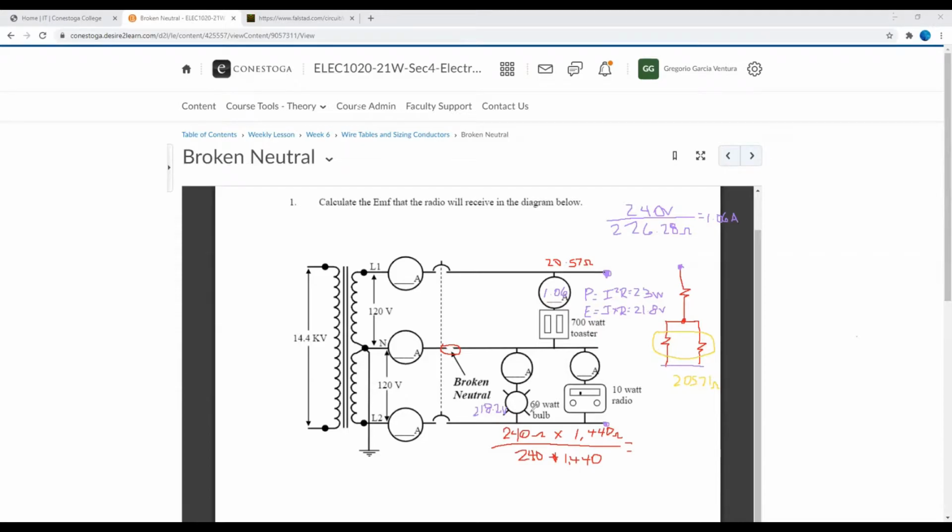So how much would be the power output? Well, we have a voltage, and we will have to multiply that voltage times the current, but I'm just going to use once more I squared R to determine the power. Or I'm just going to go back and say that power is equal to E squared divided by R. That's going to be the straightforward formula without having to do a lot of calculations.